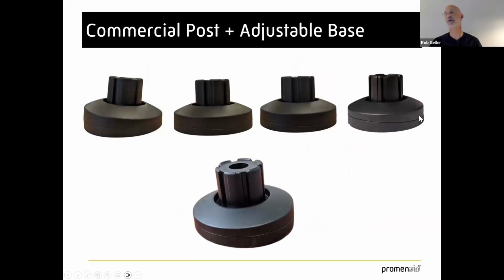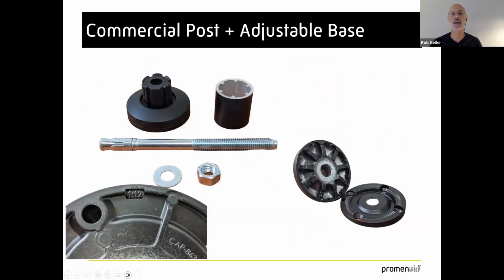You can see that this is about 3 inches in diameter, and just 2 zinc pieces cut on the diagonal. And as you rotate it, you get to the angle you need. This is what the inside looks like, and we've thought of a lot of details right here. Once those are together, if you have a 1 to 12 ramp, you just dial this, and on the underside there's a window somewhere there where you can see that, and just set it and then attach it in. Goes in with one expansion bolt into the ground, and it's real sturdy. This is a 2-inch diameter Schedule 40 pipe.